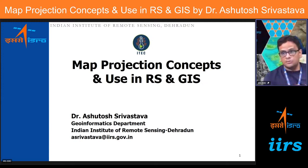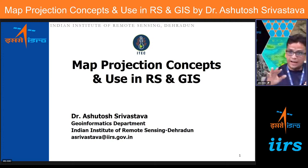But at the same time, you are comparing with satellite images. The satellite images already have the coordinate system and the projection system of today's satellite image. And you have a scanned image, and now you want to compare both. The scanned image will not have any coordinate system. So what you will do is assign the coordinate system first to that particular image, and then only will you be able to compare. Correct? So this was another example.